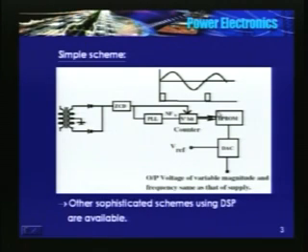Now these 0 to 511 locations should be addressed in this period. So I need to have a counter which addresses the EEPROM. The counter should start at the 0th location at the positive zero crossing and reach the 511th position just prior to the next zero crossing.